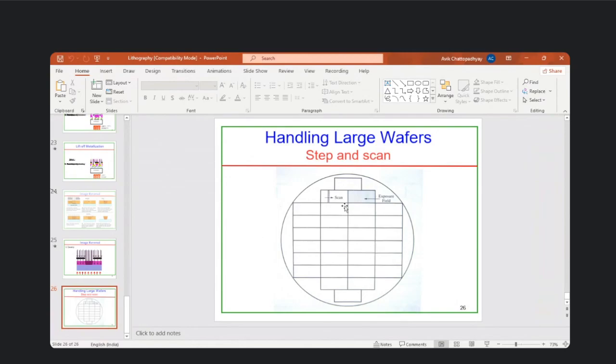You have to include the cost when deciding the price for each and every die which is supposed to be perfect. But even though they look perfect because of the shape, they may malfunction. When you go for testing of the die, even after this phase, it may so happen that out of this many, maybe 2 or 3 may not function properly. Then again you have to throw them out. So first of all, from the edges, you have to remove the material because it cannot give you a perfectly shaped die. So there is some loss in terms of cost, money.